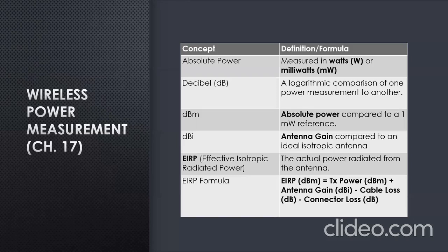In the formula here, the terms are measured in dBm, dBi, and dB, but they can be added directly because they are all on the same logarithmic scale. But there is also another way to calculate it. You can convert the power from dBm to milliwatts. How?